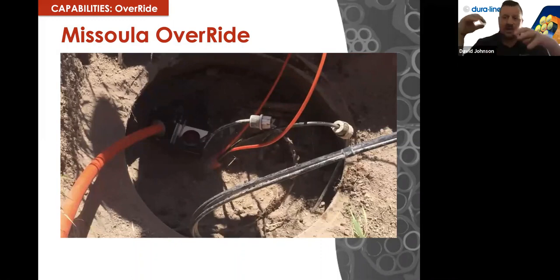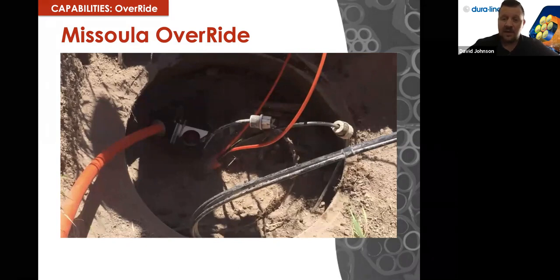And then that allows you to put the air into the whole microduct reel. On the front end of that reel, the initial portion of microduct that we push in, we've got a bullet screwed in there, so it's like a pulling eye. You're going to screw a little bullet into that. That's what will hold and cap off the microduct. And then you fill up that whole reel with air to about 100 PSI.